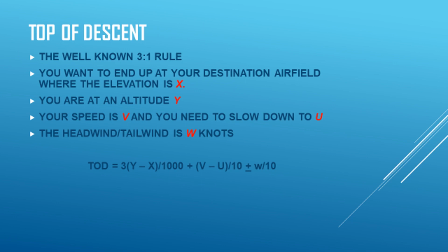So how do you know when to start your descent? Okay, there is this method here using altitude, but I'll also give you one which has to do with the time. And all these you can use as your tools to calculate, okay, when I reach this distance from this waypoint, or when I clock these hours and minutes on my stopwatch or my clock, I shall commence my descent.